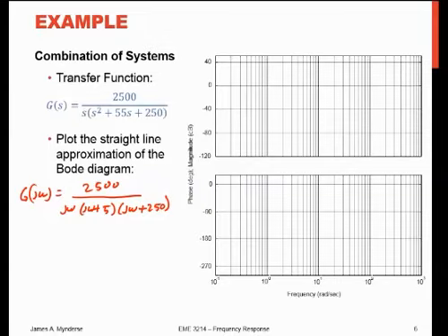Okay, if I do my magic again, I find out that my steady state gain K equals 10, which happens to be 20 dB. No surprise there, since we multiply by 20 after taking the log 10. Do that one in your head. I have poles at 0, minus 5, and 50. And we're going to do the same kind of thing we did before.